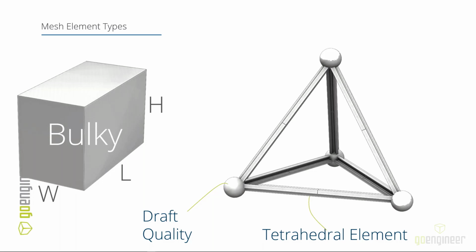The nodes, those spheres on the screen, are where the displacement, stress, and strain are really calculated for the element. If you think of just this element and we fix those bottom 3 nodes and put a force on the top one, those edges, as they move, are being described as an equation of a line. It's a linear movement.